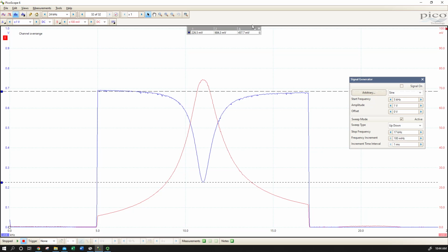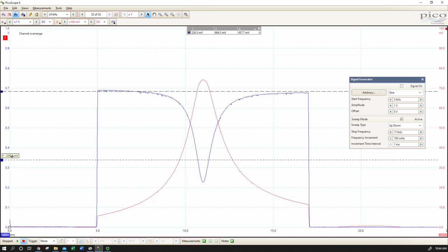In this case, what we're looking at is basically the drop in impedance as we go through. So we could look at the blue curve as the impedance of the total circuit. We're getting a reduction in that. We're getting an increase in current, which is why the voltage drop over a resistor is increasing. We can apply our 0.707 to that total peak value, 323. And so we can subtract it from our upper baseline, 458 plus. So we'll come down 138.